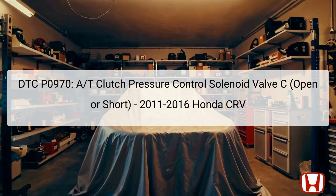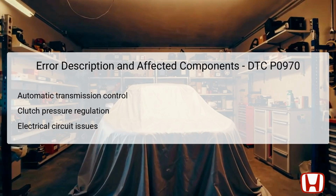The PCM is responsible for managing various functions within the vehicle, including the operation of the transmission solenoids. An open or short circuit can lead to transmission malfunctions, which could potentially affect vehicle performance and drivability. The error description for DTC P0970 centers around the AT clutch pressure control solenoid valve C, which is integral for managing clutch pressure in the vehicle's transmission system.